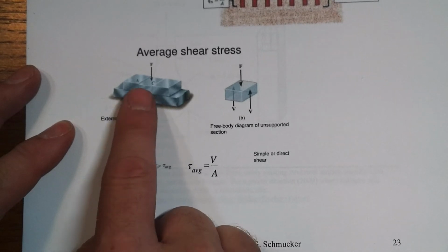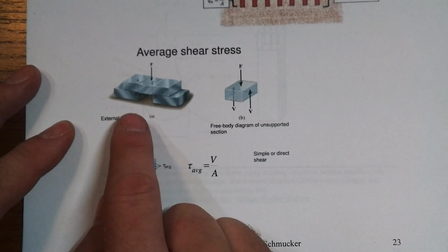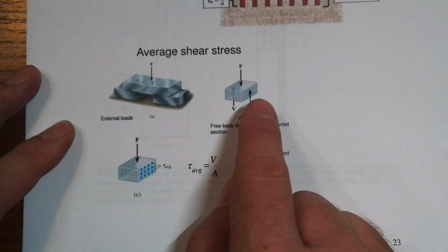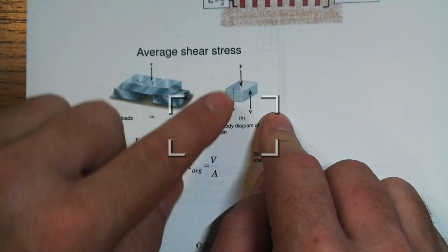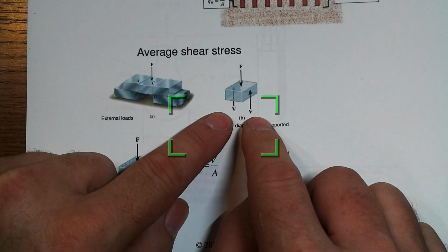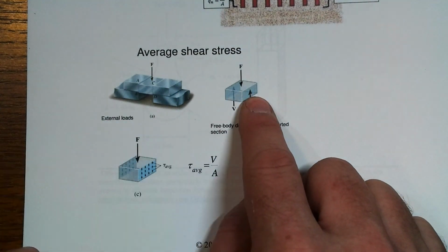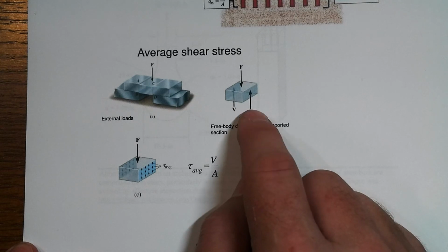This is called a punching shear, where this little piece is trying to be punched through that gap between those two supports. We pull out that little piece, and from an equilibrium standpoint, we have the total force here, and if we assume some level of symmetry, then the shear forces are parallel to those planes. That's key. Shear is parallel to, as opposed to normal, which is perpendicular to.